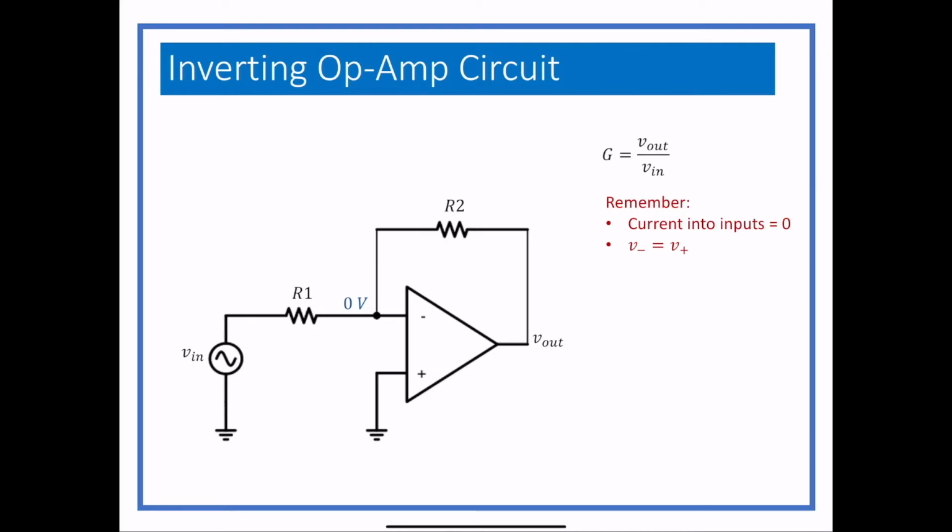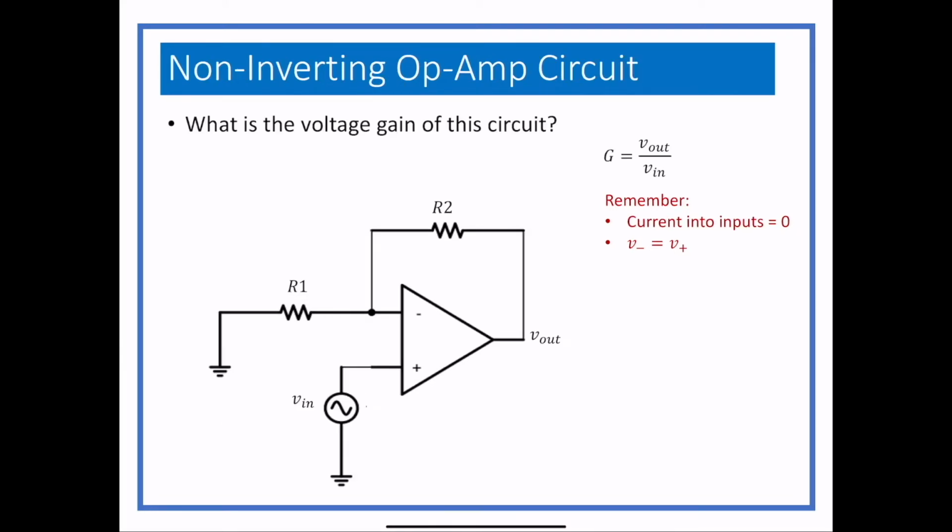We're going to take the voltage, and all we're going to do is move the voltage input to the other terminal. So we're basically just going to take those points and switch them. So now we have Vn at the non-inverting terminal, and we have R1 grounded at the other end. And that's going to make a slightly different circuit. This is the second most common type of amplifier you'll see. So once we get done with this, you can just memorize the gain value and not have to reanalyze the circuit. So at this point, it's a little bit different.